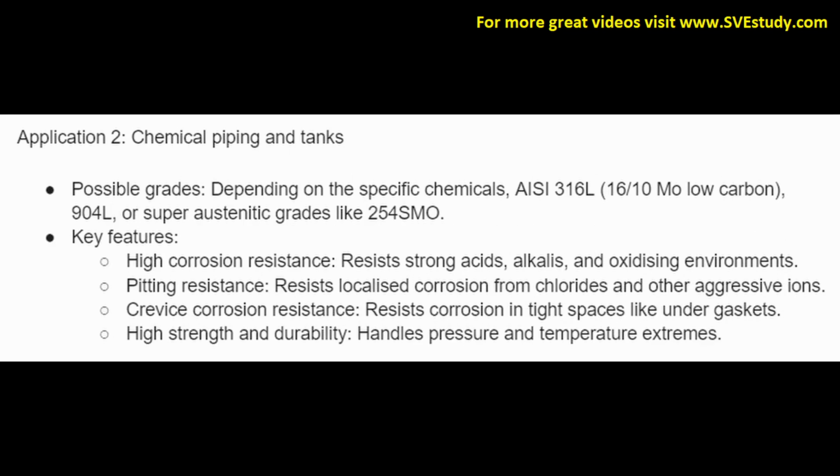Application 2. Chemical piping and tanks. Possible grades 316, 904L, or super austenitic grades like 254 SMO. Key features. High corrosion resistance. Resists strong acids, alkalis, and oxidizing environments.